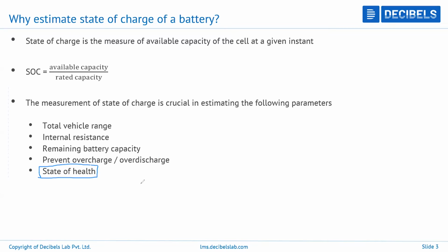If you don't know the state of charge, then you do not know the correct condition of the battery. If you don't know the condition, then we don't know to what extent the battery has degraded. Therefore, we don't know till what extent the battery can be used. So SOC can once again be used as somewhat of a derivative.